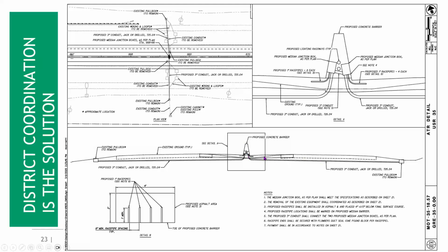So if some of this underground work can be included when these concrete barriers go in place, then underground conduits, 3-inch conduits that go over to pole boxes, then we'll be able to come in and cut our loops and piezos and have a really well run system.